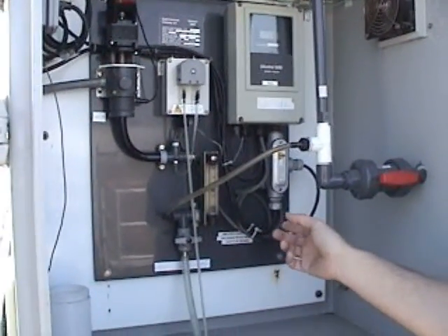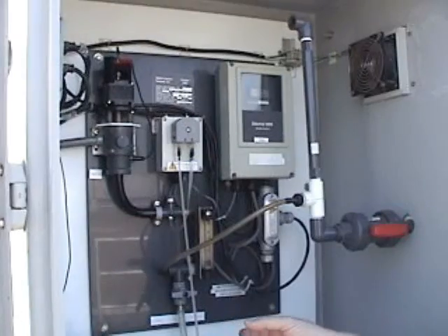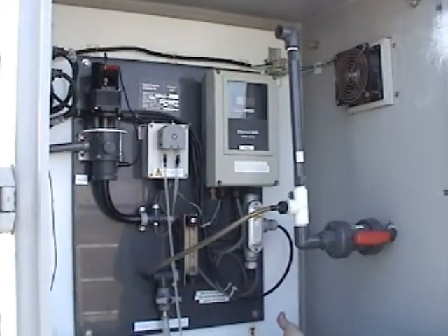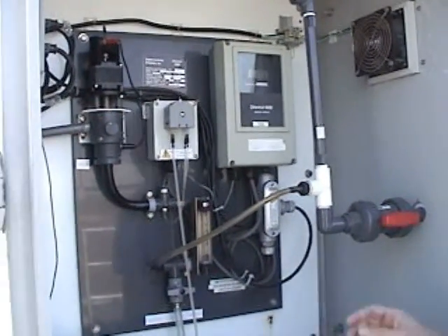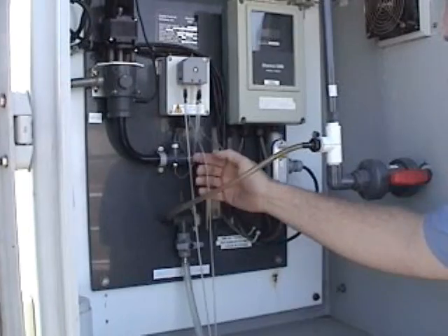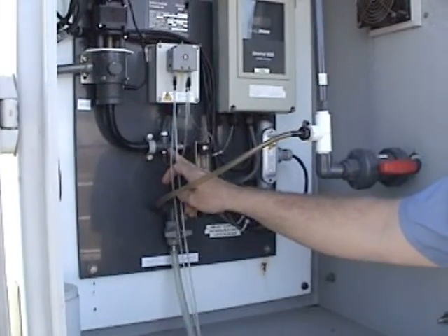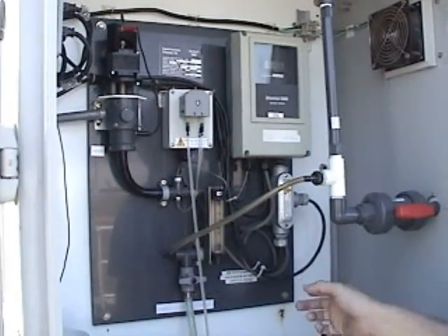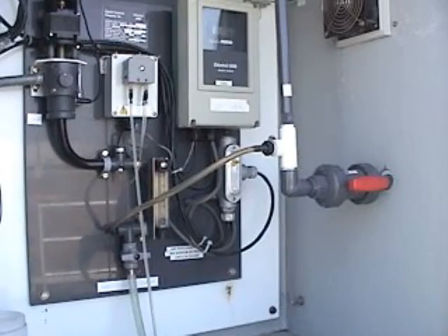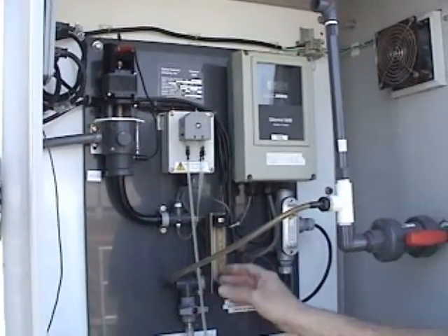One of the things you'll find is that we have 2 residual analyzers, and it's nice because the redundancy allows you to have a problem with one analyzer, and through the SCADA system you can switch to the other analyzer. It's very seldom that both analyzers will fail at the same time. One of the things that'll happen is you'll get little air bubbles in these tubes right here. That air ends up in the analyzer system and it will throw off your residual. So sometimes if you come out here and think, gosh, I checked my bleach pump, I know I've got all good set points, the pump is pumping properly, but the residual is really low, I would check for air in this line.